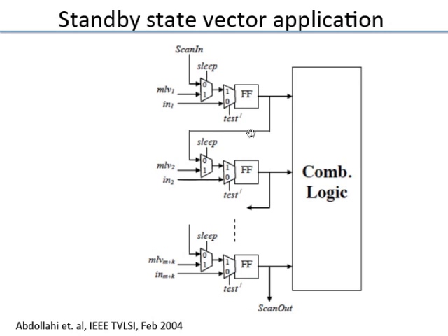No. So the question being asked is, can it check only sequential logic? Here I don't want to get into a discussion of testing and checking, but because this example uses that, I just wanted to explain that. The scan test is done to test all logic, sequential and combinational. It has nothing to do with sequential or combinational. It's just testing all gates, or as many gates as possible. You can never be 100%. You want very high coverage.